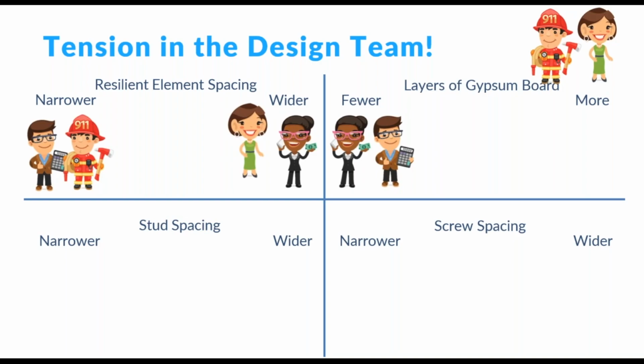And the more weight there was up there, the more stiffness they had to put lower down in that structure to resist that weight moving back and forth. So if you take weight out, then you have these knock-on effects of needing less structural integrity down below, and that saves you money, right? And those can be pretty significant if you've got a big tall tower or a lot of extra weight from gypsum board or whatever it may be.